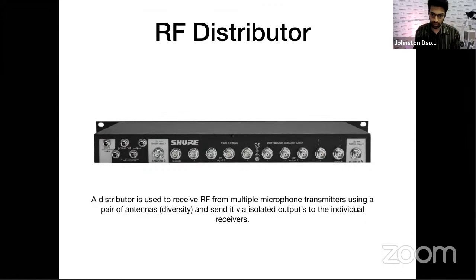Always remember, you can have only one transmitter and multiple receivers. You cannot have multiple transmitters transmitting on the same frequency. You can have one transmitter transmitting one frequency, and you can have multiple receivers receiving the same frequency. It is the same with your FM broadcast. Imagine if 5 FM stations had the exact same frequency. How would you know which frequency to choose? Alright, so there can always be one single transmitter transmitting on one frequency, and they can have multiple receivers.